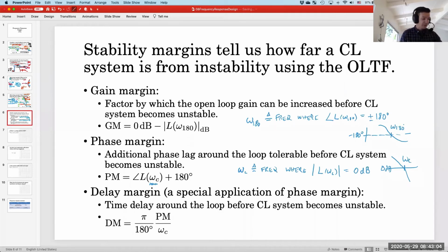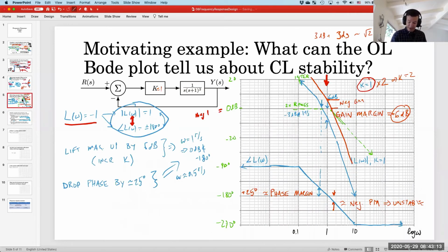Okay, so this is kind of complicated. It also suggests that it's really nice to draw your magnitude and phase plots on the same graph paper, and make them line up, right? Because to find the phase margin, I had to start with the gain plot and go down. To find the gain margin, I had to start with the phase plot and go up. If you draw your gain and phase plots side by side, it's just practically harder to do.